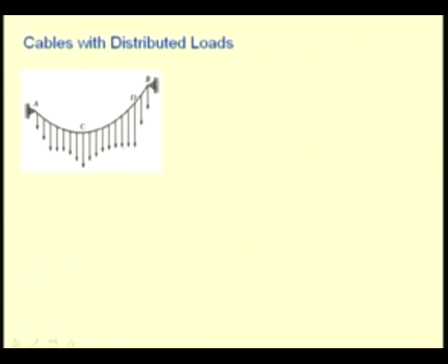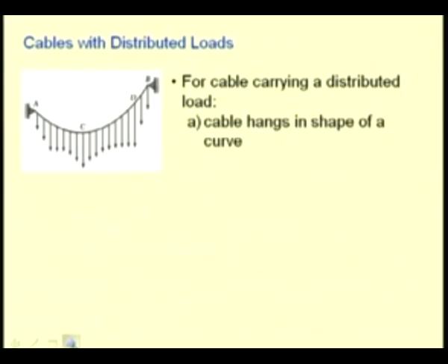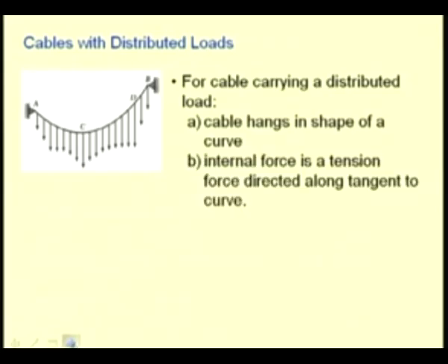It could be varying in magnitude along the cable, either along the cable or along the horizontal direction. So, we are interested to find the shape of the cable under the load, and the internal forces that develop in the cable at any location are tangent to the shape of this curve.